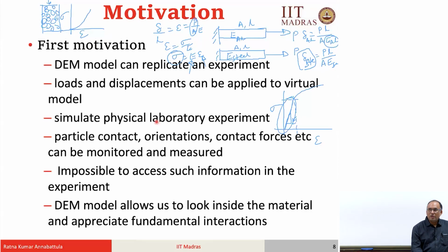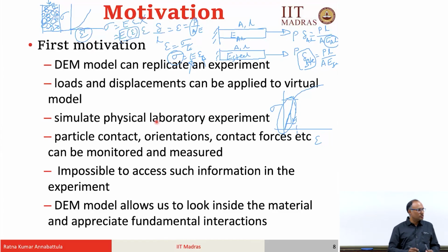So, here your constitutive relation, not contact constitutive relation, here I am talking about a constitutive relation as if this is a continuum. Now it is behaving like a non-linear elastic material whose stiffness is changing as a function of strain. Now, I cannot represent that as sigma equals E times epsilon, but I have to represent this E as a function of epsilon times epsilon, because E depends on what my epsilon is. So, that is what we call a constitutive relation.